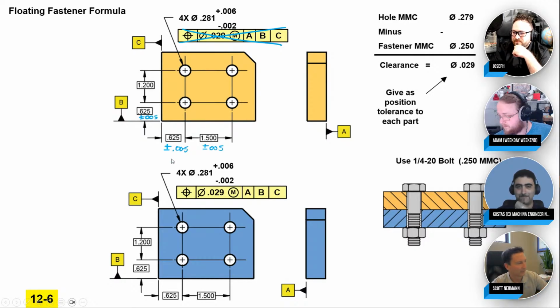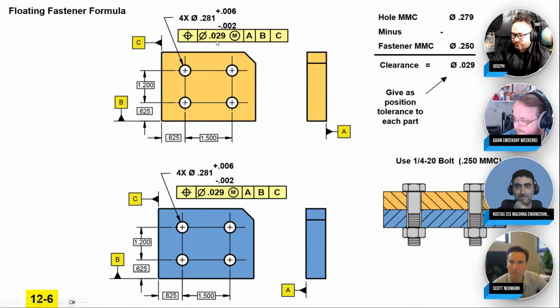I'd even say more than that when you start thinking about all the stack up that can occur. So yeah, use position tolerance, way better. I wasn't even thinking about stack ups at that point. That's a good point. You do get more after stack ups. If you just locate one hole, then this one hole, square versus round, oh okay, great, you get 56% more. But then when you go to the next hole where there's a stack up, oh my gosh, you get even more.